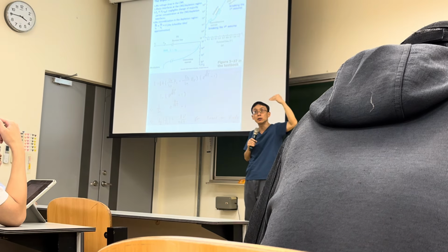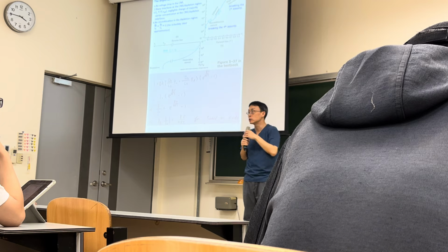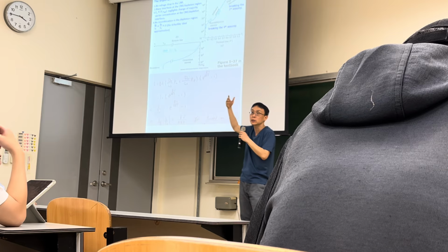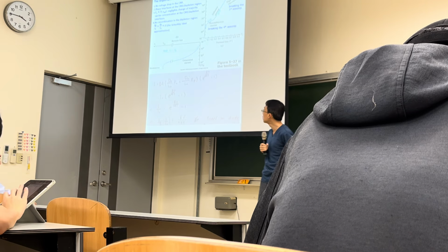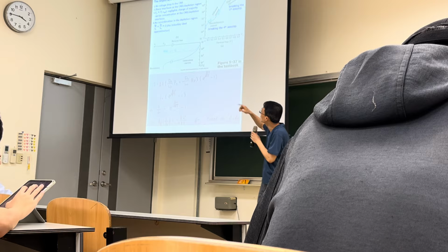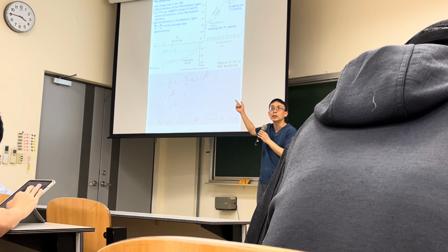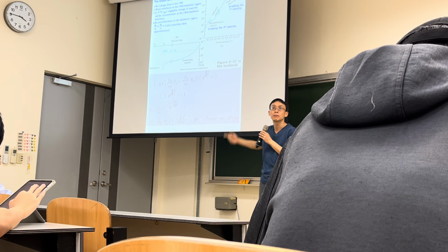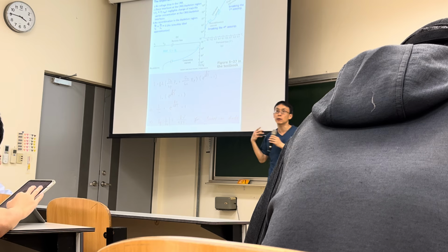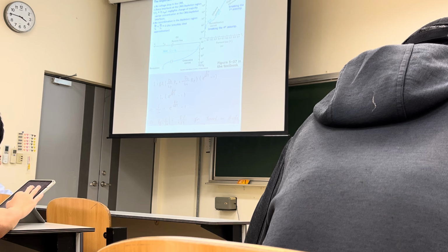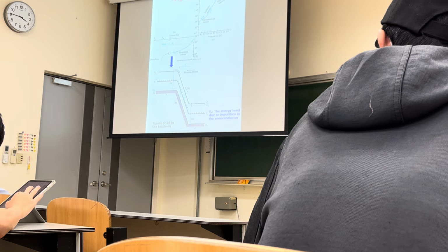But in reality, your reverse current is larger than you expect. Why? Because we have the generation currents. Something like avalanche breakdown, but not exactly the same. Okay? So here we want to tell you the origin of this generation current on the reverse bias.